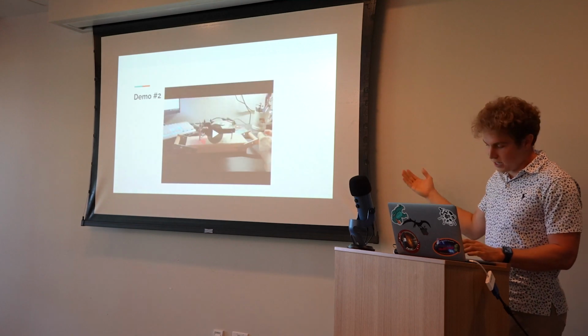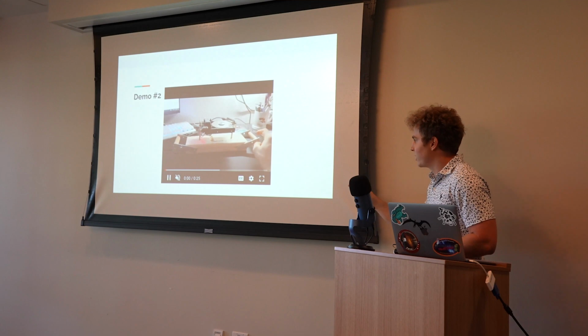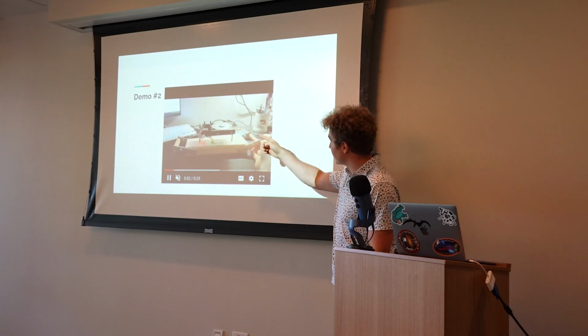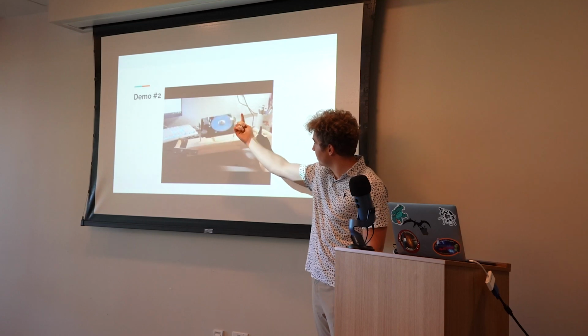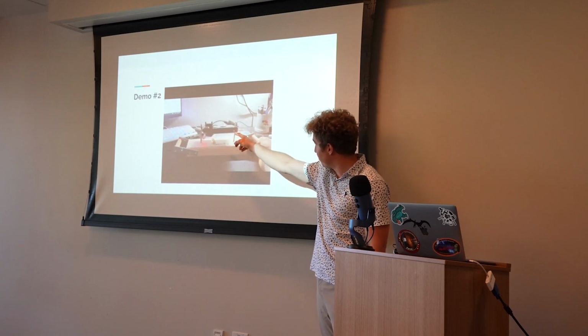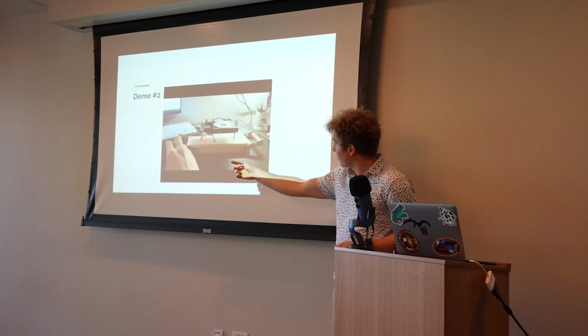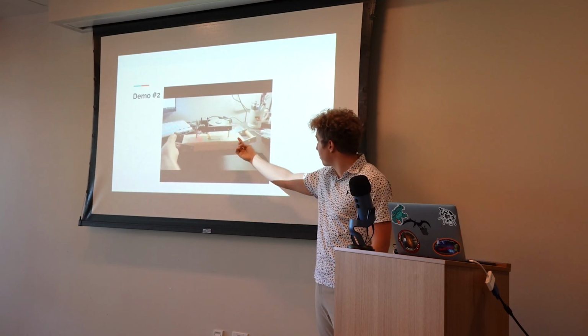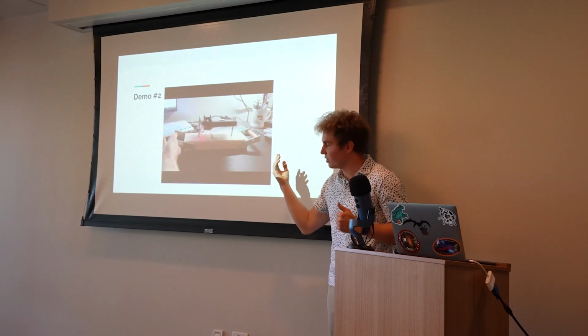This next one here is exactly what I talked about with the helicopter. It's spinning counterclockwise. I put an upward force here, and what happens? It spins, goes up like that. So the back comes up, again, 90 degrees ahead. So then what happens when I put an upward force here? The part facing us goes up. 90 degrees after the force is inputted, you see the movement.